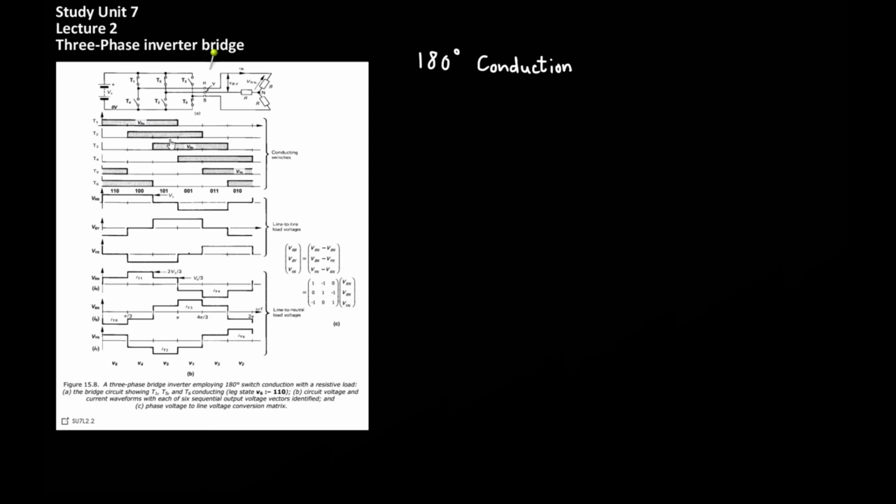So there are several ways to describe the behavior of the switching cycle. I'm going to focus on the more digitally inspired way of describing the switching behavior. During the entire cycle there are 6 different intervals. In other words, there are 6 periods where there will be 6 unique switch combinations, and these 6 combinations can be enumerated digitally with binary codes. So what this means simply is that each particular state has a unique binary identifier.